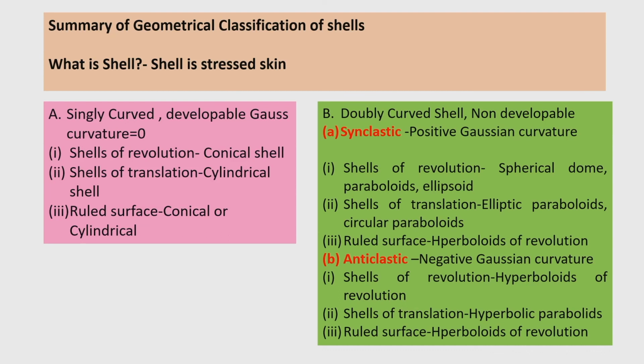Okay. So, today I have given the classification of shell based on geometry. I have introduced the geometrical parameters of the shell, mainly the curvatures and how to find out the principal curvatures based on the curvatures in two orthogonal directions and the twist curvature. And then I used one important parameter, that is the product of two principal curvatures, known as the Gaussian curvature, to classify the shell.